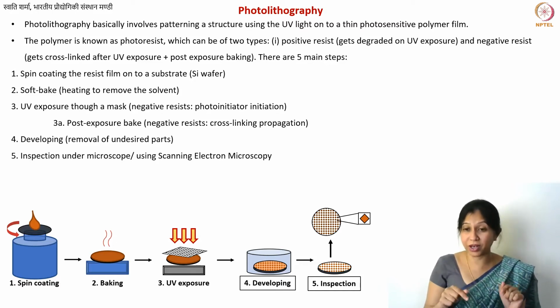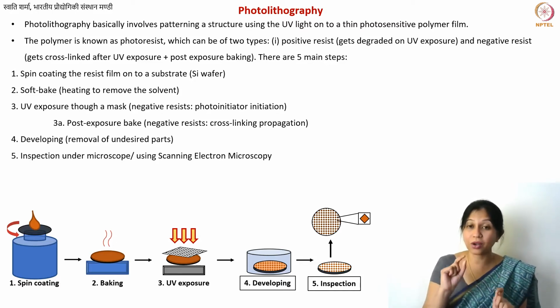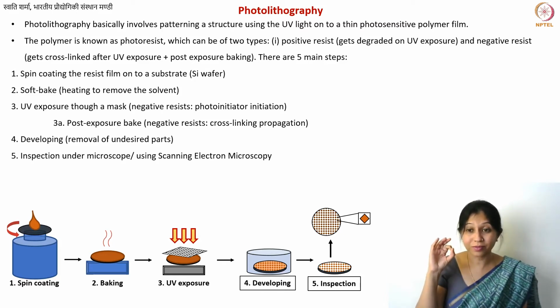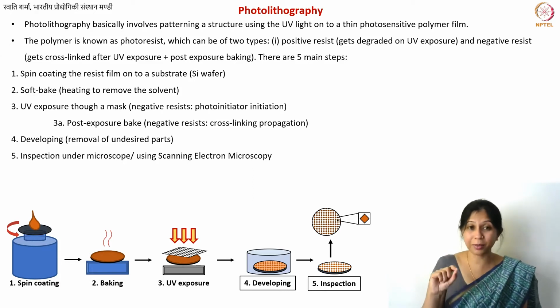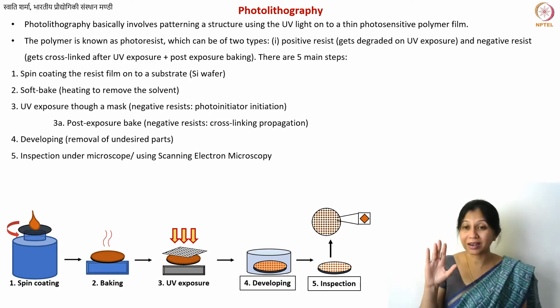In our case, when you want to make glassy carbon structures, now you're going to take these structures on silicon wafers, either the entire wafer, or you can cut it into smaller pieces if it's a batch fabrication technique. Put it inside the furnace, and make sure it's a tube furnace and you have an inert environment, and then heat it up to what temperature now? Well, 900 can already give you a reasonable carbon if the structure size is small enough. If it's in the micro domain, typically 900 gives you reasonable glassy carbon.